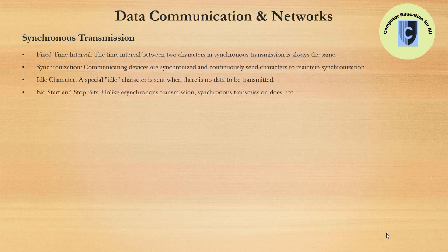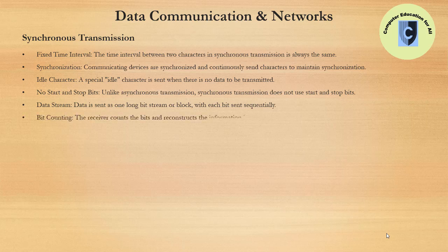It sends data as one long bit stream or block of data, and each bit is sent one after the other. The receiver counts the bits and reconstructs the sent information in bytes. It is essential that timing is maintained, as there are no start and stop bits and no gaps. Accuracy is dependent on the receiver keeping an accurate count of the bits as they come in.